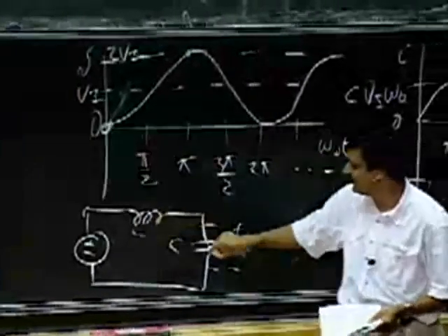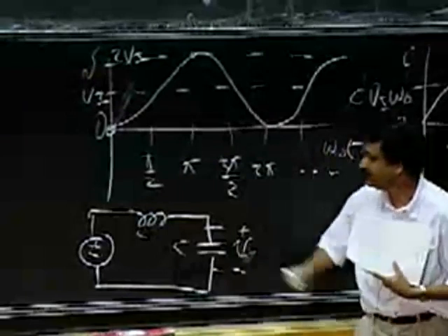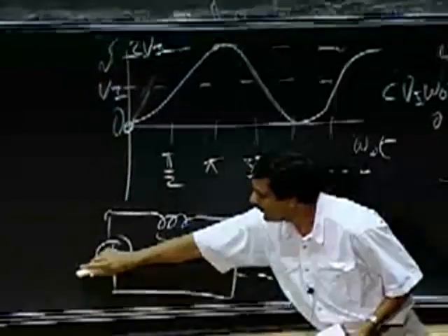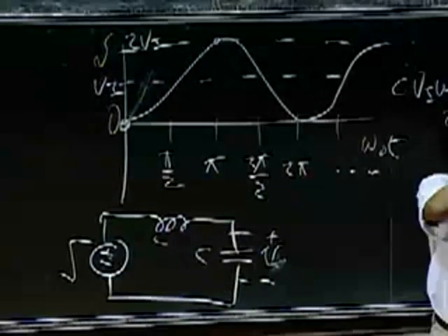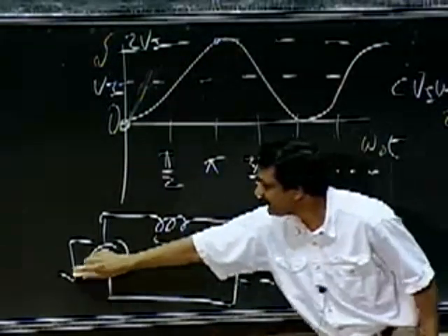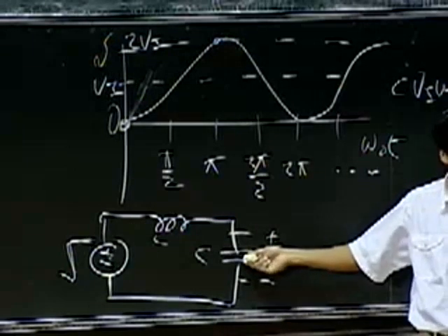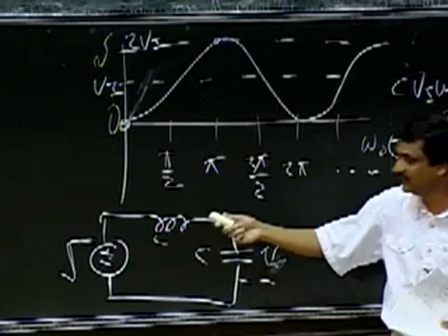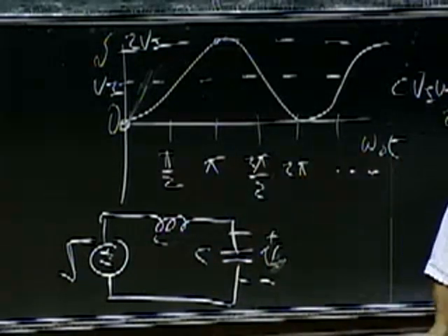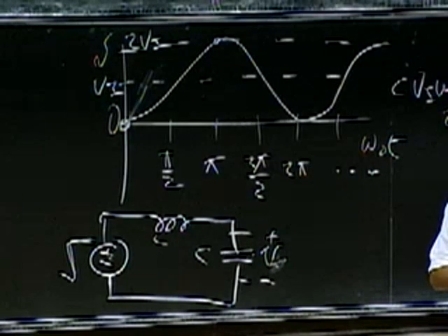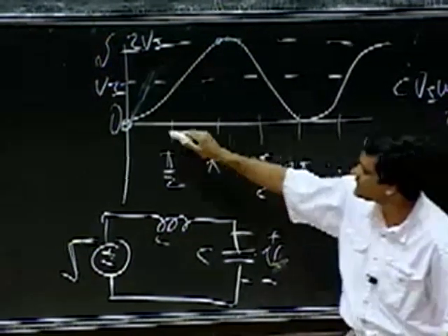Start off with both of them having the states 0, 0 current, 0 voltage. Apply a step here. Boom, the step comes instantaneously to VI. Notice that the capacitor voltage cannot change instantly, unless there's an infinite pulse of a sort. So this cannot change instantly, and so its voltage starts off being 0.